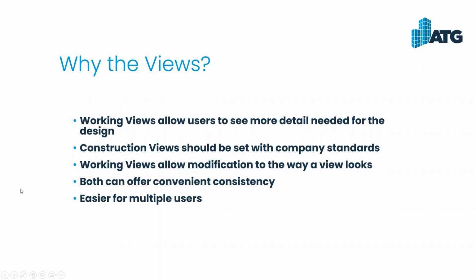So you really want to avoid adding annotations to working type views, because remember, annotations do not carry over from one view to another. Only if you have duplicated with detailing will it bring over the annotations, and that's kind of a one and done type thing. Once you've done a duplicate with detailing, you've got to go in and add the details to that newly created view. So that's why you want to stick with the detailing in construction views, and really the design aspect in the working views.